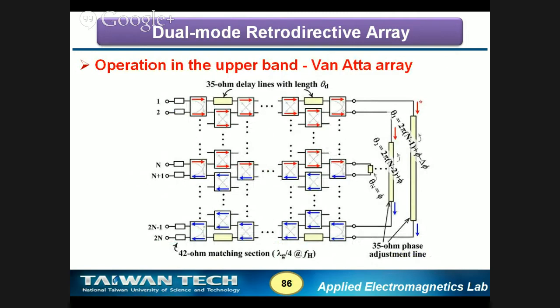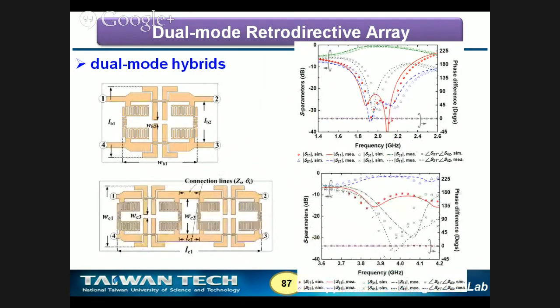We don't introduce any active switches. We don't introduce any active MEMS or diodes or anything. We just use the concept of the multi-operational mode single-stage transmission line, and make it open circuit, especially for this shunt element, at a single frequency. Then this part will become invisible.